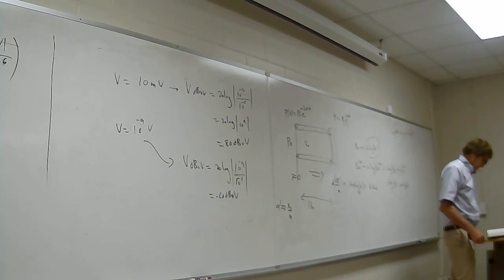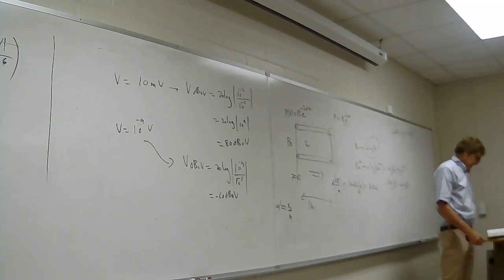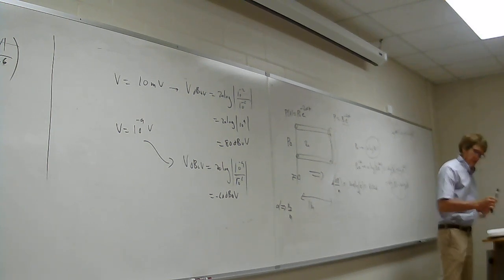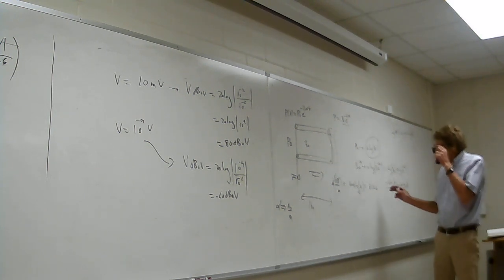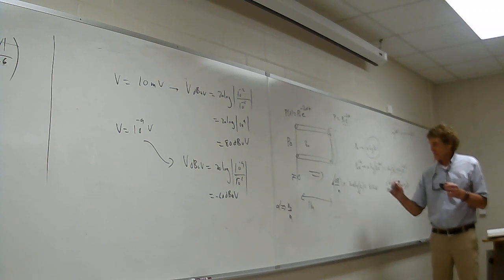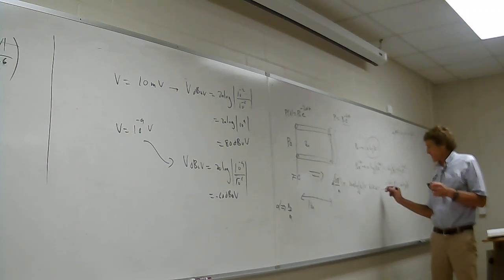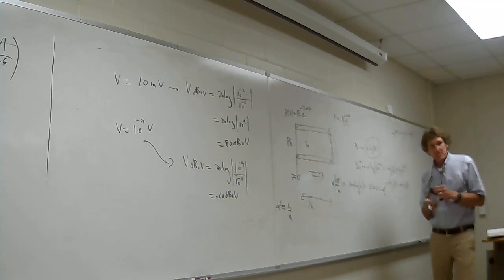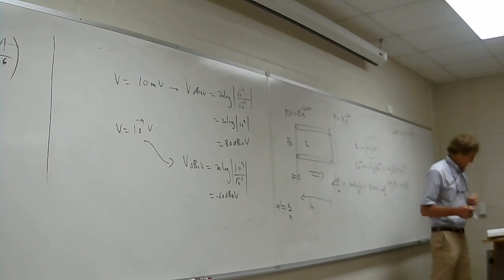This is page 48. And he just leaves it in terms of a Neper versus a dB, but I like to do it per meter, so 8.686 alpha is equal to the attenuation in dB per meter. You all see that there on page 48?